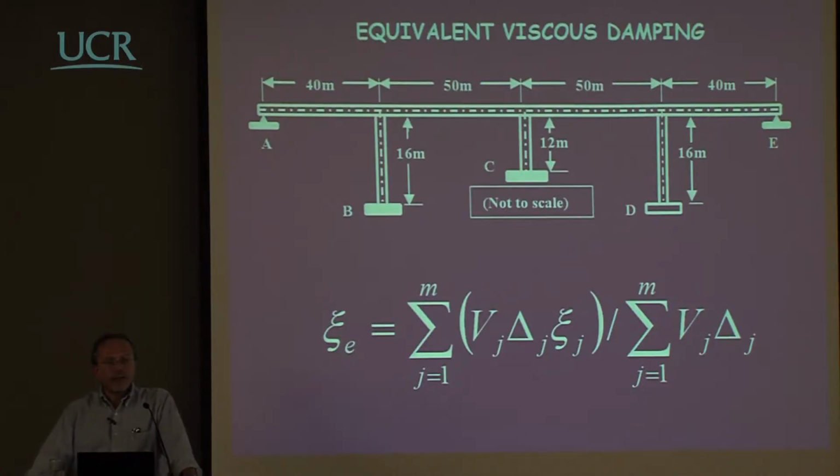That's why, in terms of added damping, a deformable isolator on top of a stiff pier is much more effective than the opposite. Because you want to concentrate the nonlinear response on the isolator, and therefore there is where you have the damping, and there is where we want to concentrate most of the displacement.